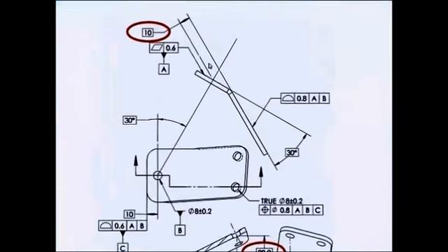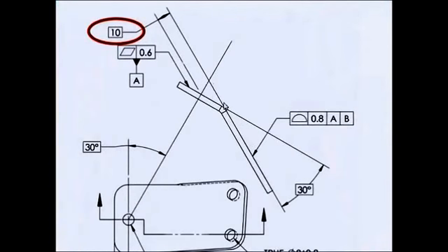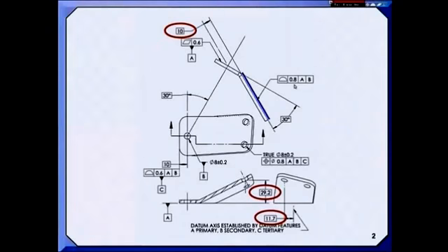Keep in mind that this 10 millimeter dimension is going to the surface, and that surface isn't going to be exactly at the basic location when you're holding the part. There's a profile of 0.8, which means that the surface could be 0.4 that way or that way. So trying to find this point in space can be difficult. A different approach is,